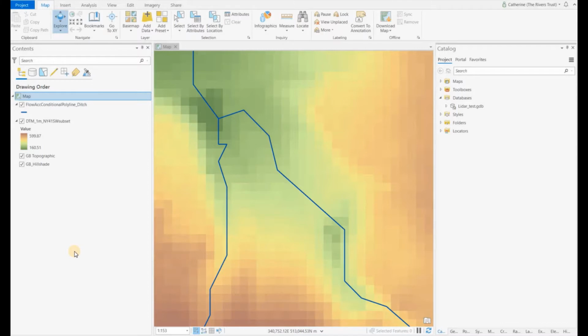In this video, we're going to look at how you can use LiDAR to estimate storage volume of a pond that you might be looking to create for NFM or other purposes. In this example, we're going to use 1 meter LiDAR because that's what most people have access to. But if you've got higher resolution LiDAR or, for example, height data from a drone, then that would be better because obviously the more detailed your input data is, the more accurate you're going to get in terms of estimation of storage volumes.